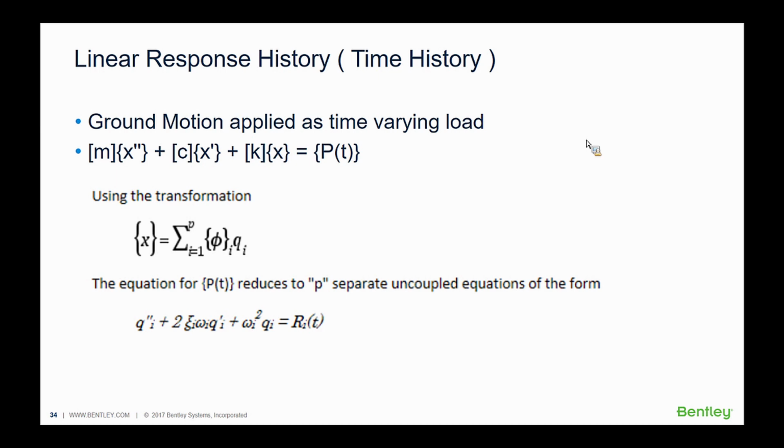Just as in case of a response spectrum analysis, the mass and stiffness modeling are critical for calculation of the mode shapes and the frequencies which form the basis of the modal superposition. So everything that we have discussed so far related to modeling of the masses and stiffness holds true for the time history analysis as well. The main difference between response spectrum and the time history loading is that for time history, the loading is specified as a time versus acceleration data, whereas for a response spectrum, the loading is entered as a spectral acceleration versus time period data.